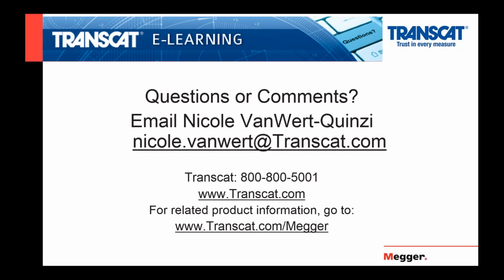Me personally, I would go with a VLA battery in a solar site because of the simple fact that it's going to be less temperature sensitive, and I will get a longer lifespan out of it as well. Again, a VLA battery, you're good for 20 to 25 years on those. But the important thing is to get the right chemistry battery.